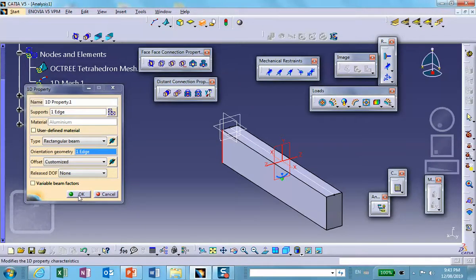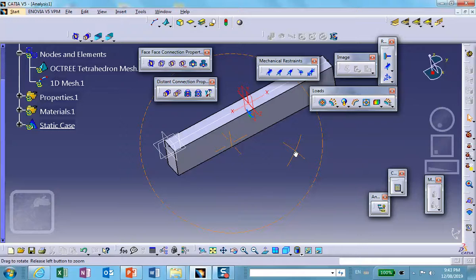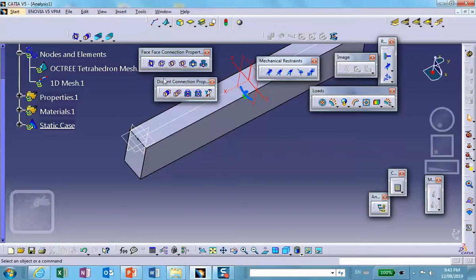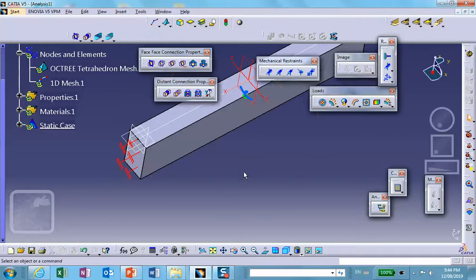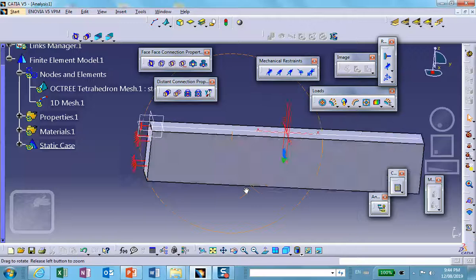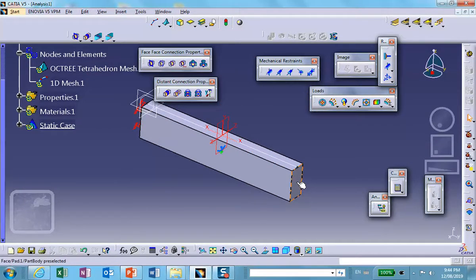Okay, now if I run the problem, well, first of all, let's apply the restraints and the loads here. So this left face of the block is clamped, and the top end, or this end of the line, is also clamped, because those are beam elements right there. You can see that. Now, when it comes to applying moment, I have a choice of applying 10,000 on this, or 10,000 on the beam, or 5,000 on 5,000, because eventually I'm going to tie these two together. So let's do 5,000 on 5,000.